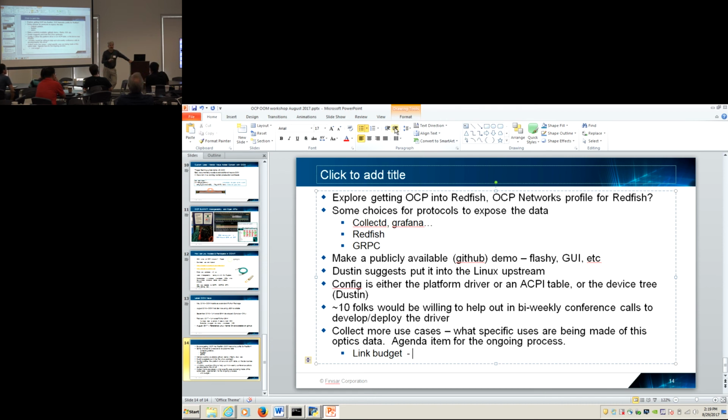I have to confess my ignorance. I'm a server operating system guy who's been asked to help the optical vendor do some operating system kind of stuff. I don't know what you mean by link budget. Between the two optics, when you hook up the optical link in the data center in the same rack, it doesn't matter, it's okay, but when the distance goes longer than that. There's a minimum power that a transmitter sends. Exactly. And there's a minimum required receive energy. The difference between those is some number of dBs of loss that you can suffer in the fiber plant. That loss comes from the fiber, but it also comes from technicians who clean the jumpers on their shirt.